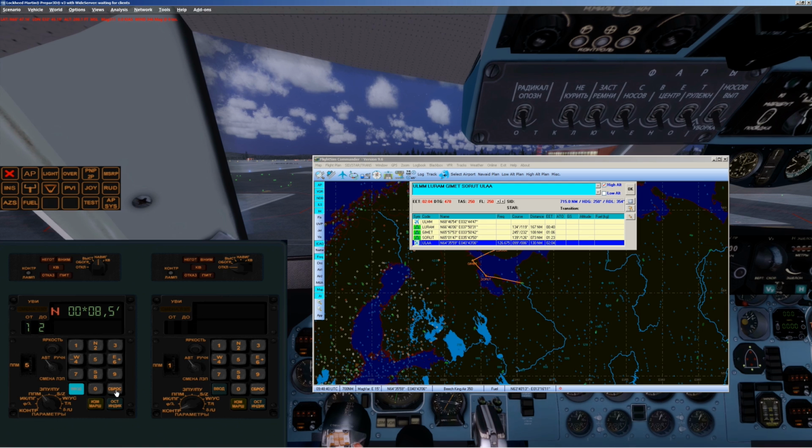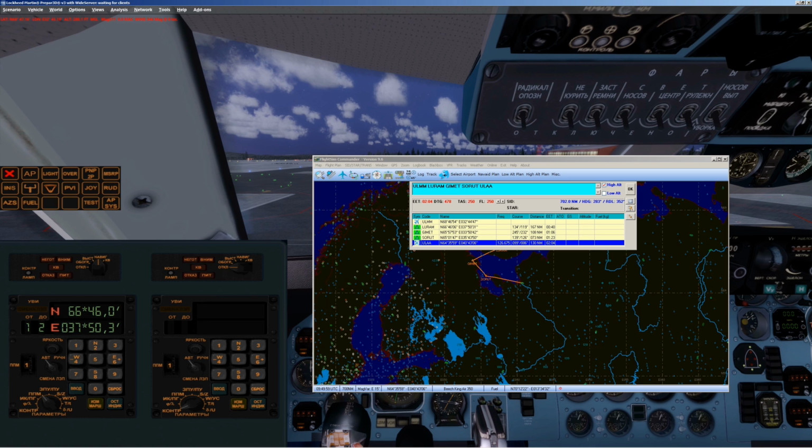You press this button, it's the reset button, and that's all. Then you do the same steps on the second gauges: switch to heat position, wait for the not ready lamp to illuminate, switch to setup position, and set the coordinates of the aircraft, north.